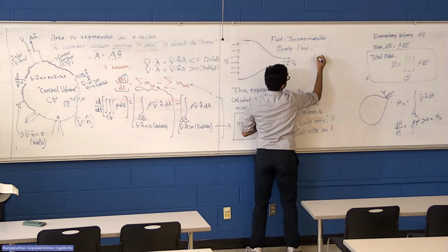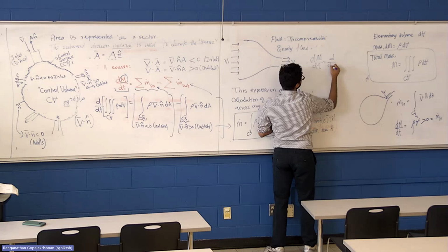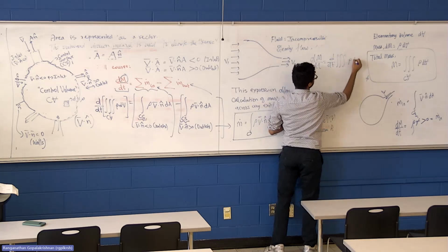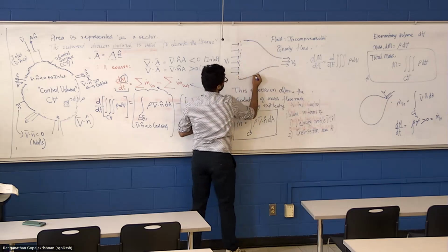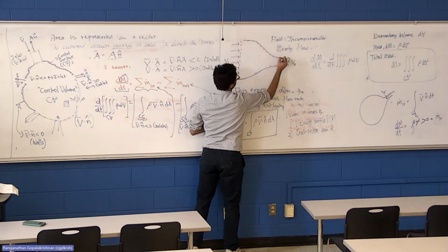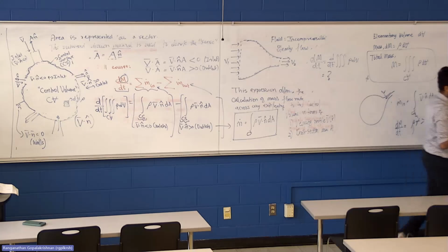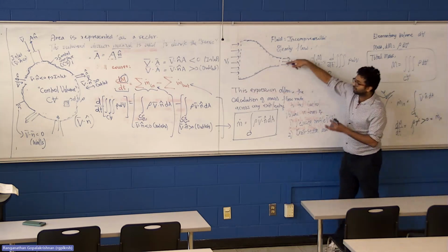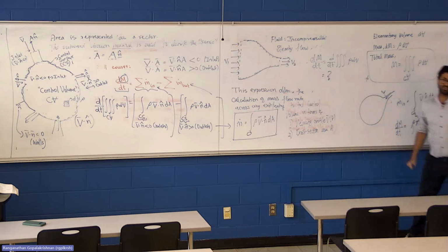then can you think and tell me what is the rate of change of mass, or d over dt integral rho dV, for this system where my control volume coincides with the shape of the nozzle? What I want from you is tell me what is the rate of increase or rate of change of mass for this example. Steady flow, water comes in, water exits, and it will accelerate because it's a nozzle, the cross section is dropping. What is the rate of increase of mass?